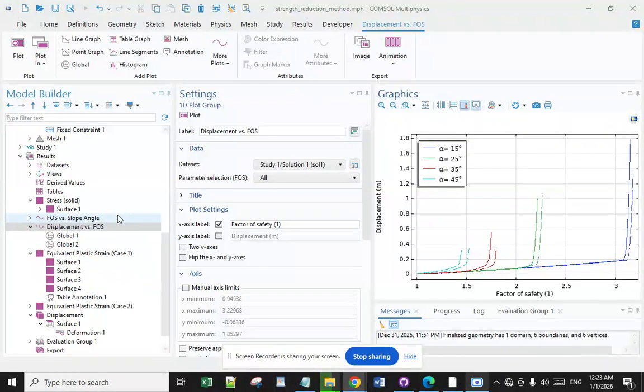Then, a numerical method was constructed based on the computation of the mathematical mechanical relationship between FOS and the mechanical parameters, and the stability of a slope is estimated based on the Mohr-Coulomb yield criterion. Finally, the double strength reduction coefficient method proposed in this study, the limit equilibrium method, and the traditional finite element strength reduction coefficient method were applied to non-homogeneous slopes and slopes containing a soft underlying layer for comparison, and the difference between them was within the range of plus or minus 5%.